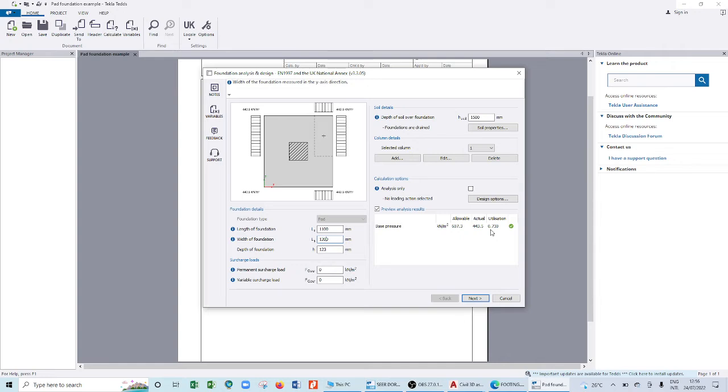Crossing sign. Now that crossing really means it has failed. Now what we call the variation is that the size of the footing that you use is smaller. So you realize, if you remember the pressure, with a smaller surface area, you exert more pressure. So the footing will exert more pressure on the soil.